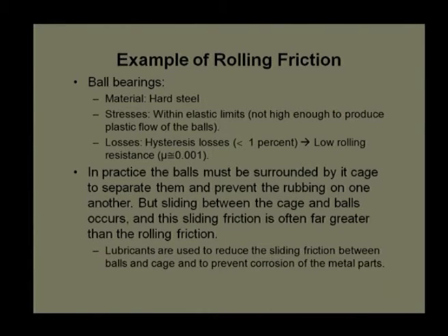However, we know the rolling element bearings come with cages, separators. We provide a cage to separate the two rolling elements. The reason being, if one rolling element is disturbing the other rolling element, in what we call fully complement bearings, load carrying capacity will increase, but there will be chances of more friction due to the rolling between two surfaces itself. It will start retarding each other's motion, and then will create a high coefficient of friction at the interface.